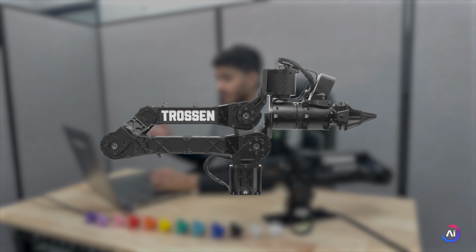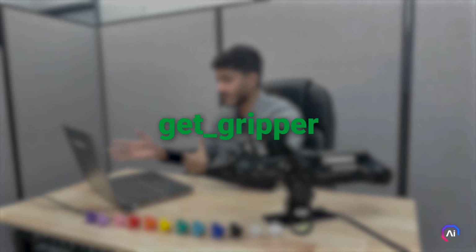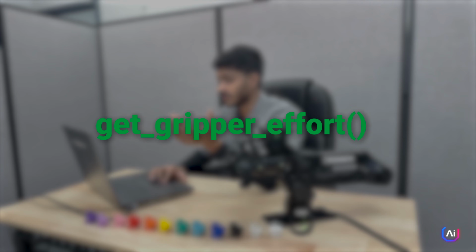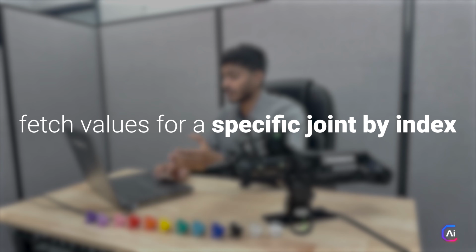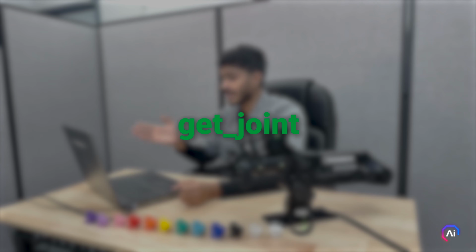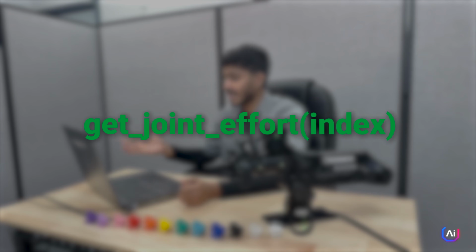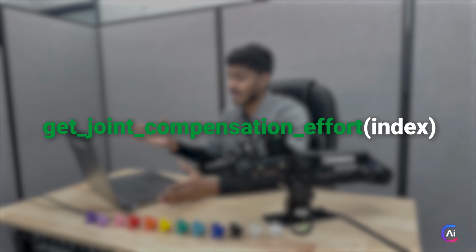If you want data for just the arm, excluding the gripper, use the get_arm prefix. Get_arm_positions or get_arm_driver_temperatures. To access values for just the gripper, use the get_gripper prefix. For example, get_gripper_effort or get_gripper_rotor_temperature. If you need to fetch values for a specific joint index, then use get_joint methods like get_joint_position, get_joint_effort, get_joint_compensation_effort, where you pass the index as the argument.